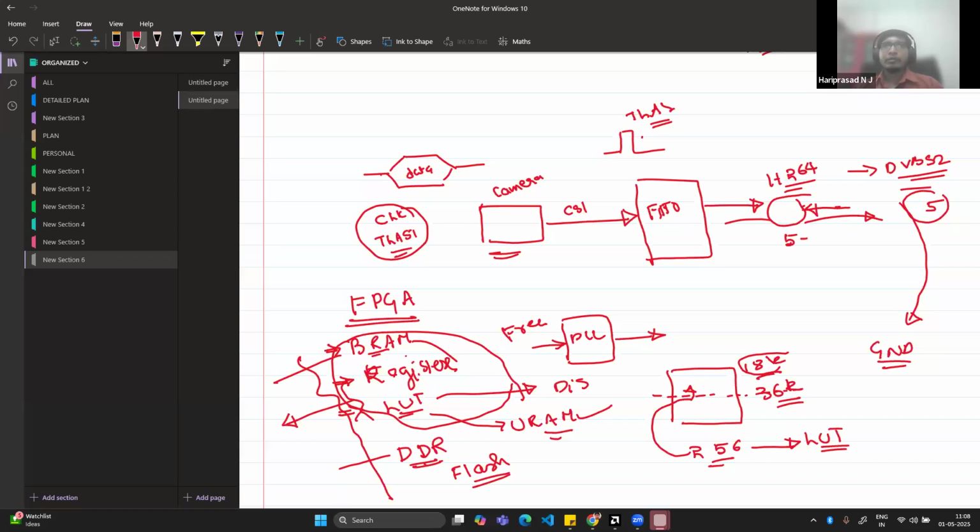In one scenario I was designing a CIC filter. We worked almost 3 months optimizing that CIC filter, because the whole design was not fitting within the FPGA, right? We were doing gate-level analysis of every part to see where we could optimally map the whole thing.